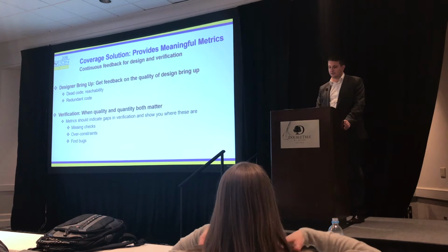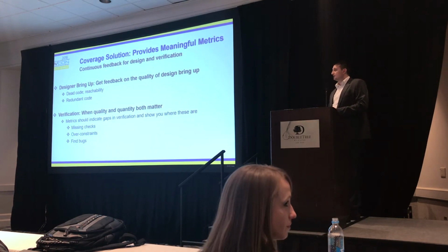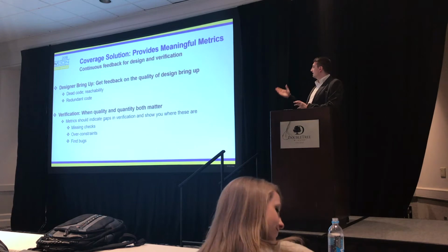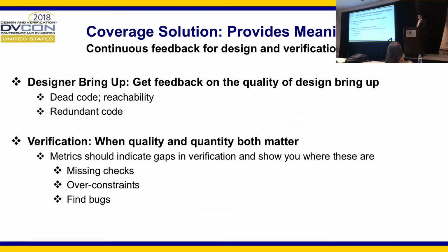And if we talk about designers, let's say you have your designers doing nothing but design, you can still have a designer bring up the tool. As I mentioned just before, you can still have dead code and reachability checks running. You can identify redundant code. So it's still valuable information, and it can still unearth some bugs in the design that you don't later have to capture with complex test benches and waste valuable verification time. So designers can get rid of these quickly. And if you have designers that maybe run some inline assertions as well, even better, because you can already quantify these assertions and start verifying your code even during the design cycle.